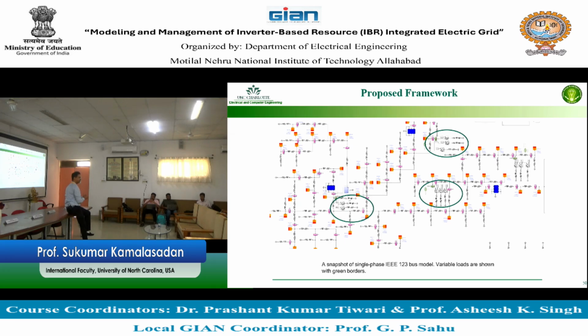Capacitor bank is also included. So these are legacy. So if I ask you to name a legacy controller in a power distribution system, what do you control in a power distribution system? Voltage, right? Basically. What else do we have? So the interaction with the legacy controllers. Basically, one of the legacy controllers is like a transformer tap, and when you are controlling with the DER, you are controlling the inverter to manage the voltage.